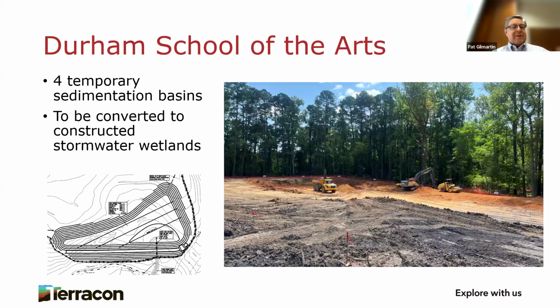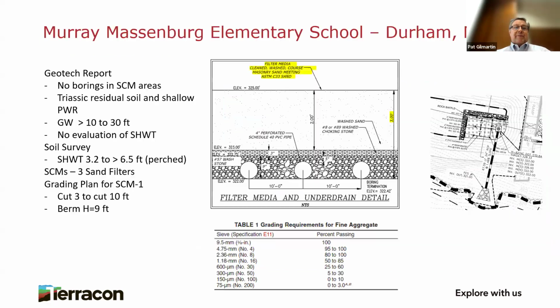All right, Durham School of the Arts, it's currently under construction. We're not using strippings. We're saving the material. The contractor is currently installing the temporary sedimentation basins, and we've been proactive enough with the project team to make sure that we're out there monitoring that work. And because we know at the end of this, it's in the city of Durham, we're going to have to do one of those city of Durham certification forms. But whether you're doing a certification form or not, oftentimes as material testing firms, geotechnical firms, site civil engineers, we're asked at the end of construction, hey, let's certify or confirm it was in compliance with plans and specs. You've got to be out there when it's being constructed, not after the fact, to do that.